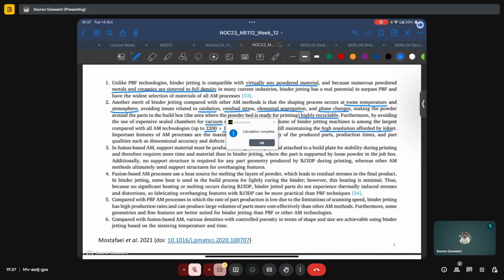Previously we saw for other technologies, such as powder feed based AM or other processes with similarly large build chambers, that there was a trade-off in resolution. The resolution was not as high compared to powder bed processes, but then because of the requirement of vacuum in powder bed type processes, the build chambers were small. Binder jetting combines the best of both worlds.